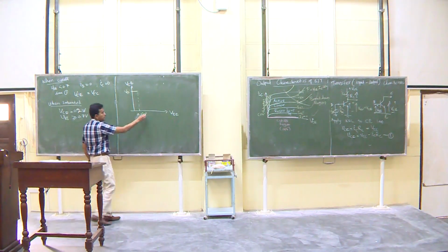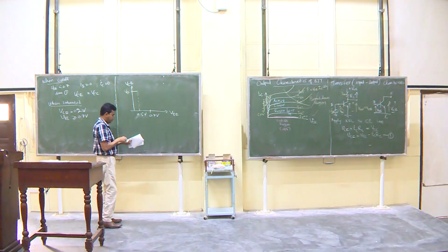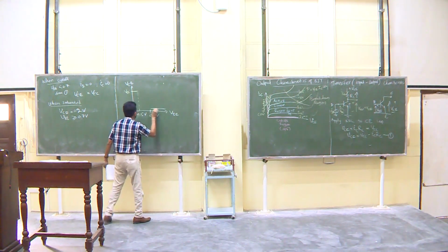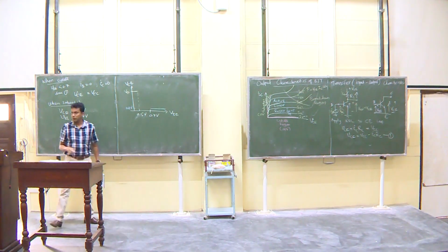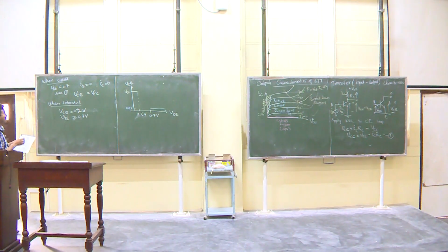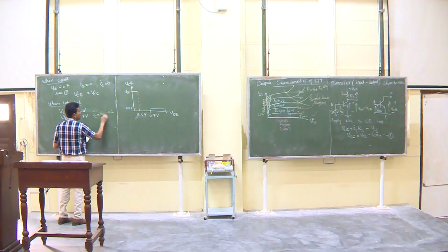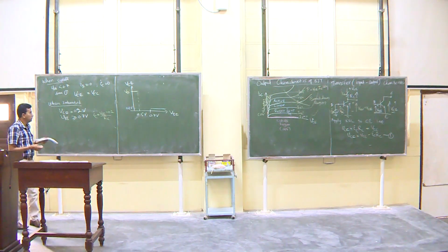Okay, so 0.7 volts and more, I have saturation, this is about 0.2 volts, correct. So, that is what you have. Now, you have two regions covered, right. Under this situation, IC is equal to VCC minus 0.2 divided by RC, the current, if you want to find the current, very simple, right.